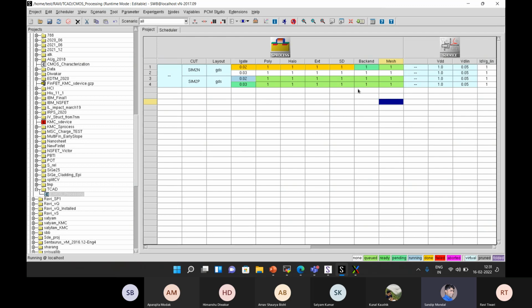For example, if you have a 100 nanometer thick oxide on a capacitor, and you are applying, let's say, 0.1 volt, you are not going to get anything actually, because there is no leakage from there. If you are trying to measure the leakage current and there is no leakage, there is nothing you can get. So you need to have parameters close to what is useful to get some results from the devices. So the right set of parameters is very important. Even if it is not exactly right, it should be close to what the device requires.